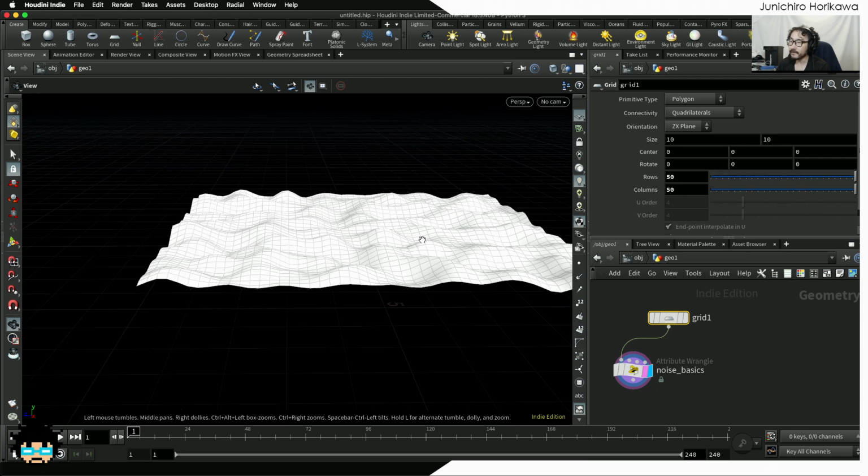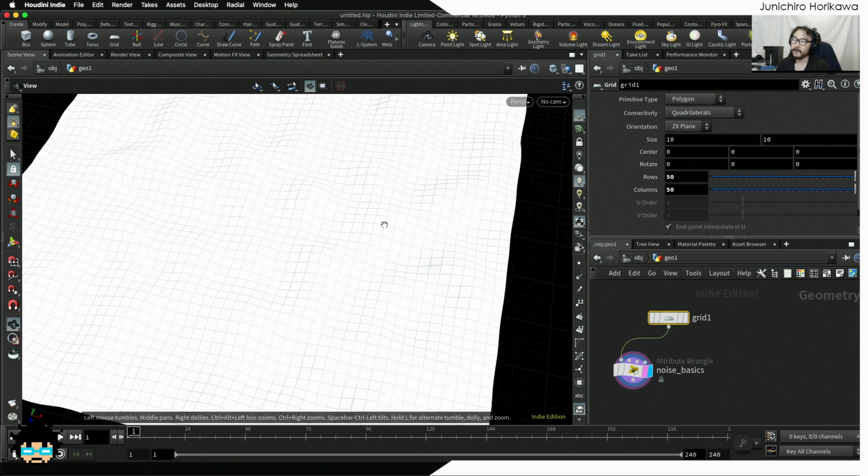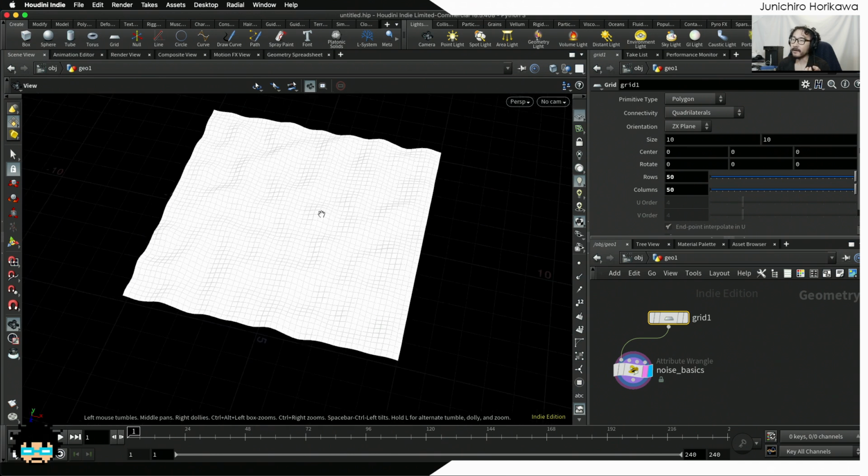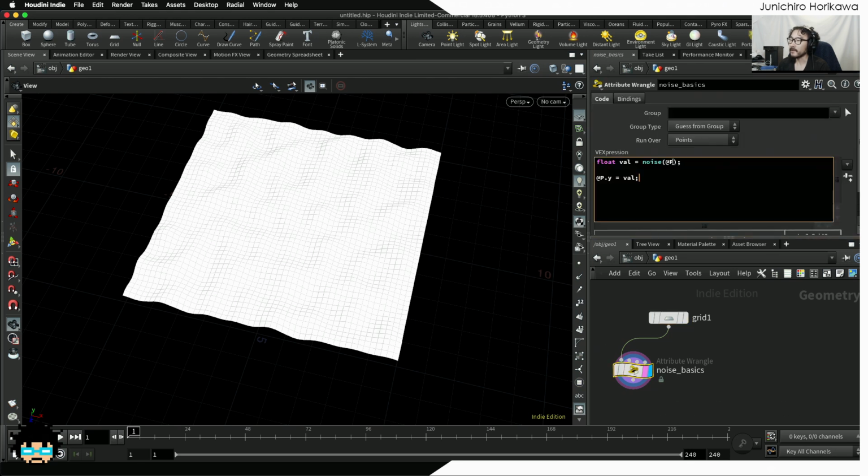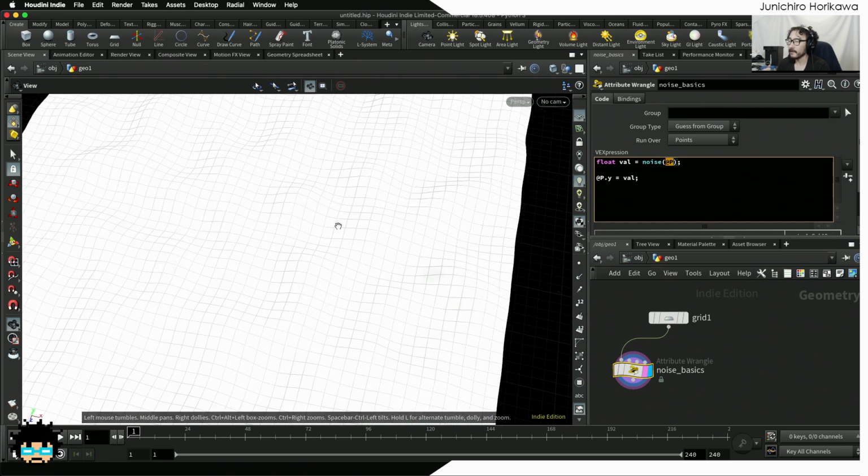Now, you can procedurally control the distance without changing the original geometry itself, by just multiplying the input right here. I'm using the @P attribute, which is the point location, but by multiplying this by some scalar value, you'll be able to easily scale down or scale up this location value. And by doing it, you'll be able to control the size of this wavy mountain. Let's see how we can do that.